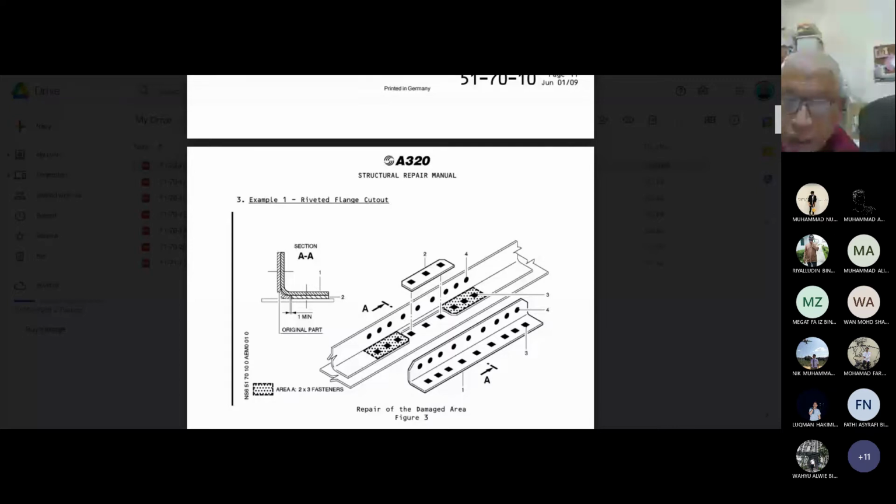If you notice later on, the filler is only required when you have damage on the horizontal flange and a doubler covering it. Imagine if you did not have this filler and left that area blank: any water, moisture or dirt will go into the area.